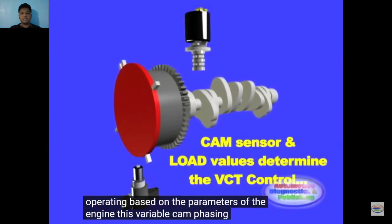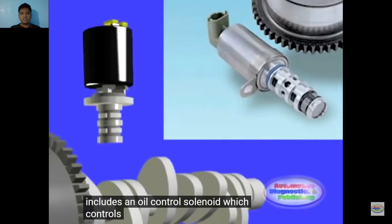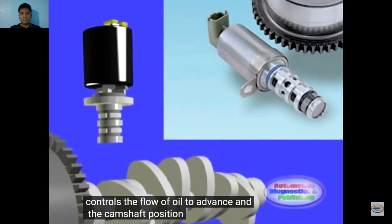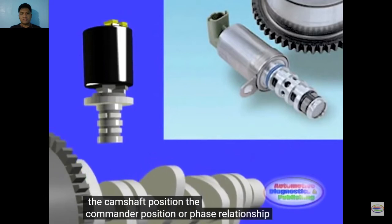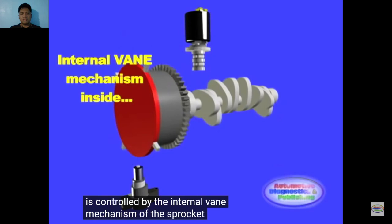This variable cam phasing system includes an oil control solenoid, which controls the flow of oil to advance and retard the camshaft position. The cam angular position, or phase relationship, is controlled by the internal vane mechanism of the sprocket.